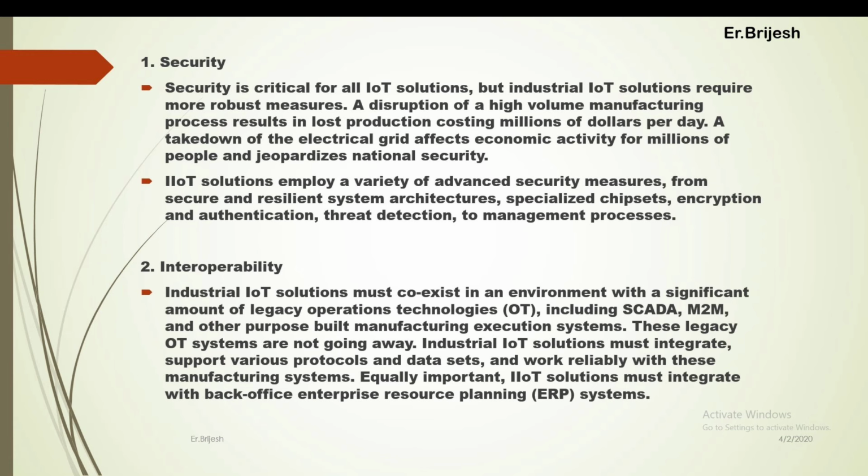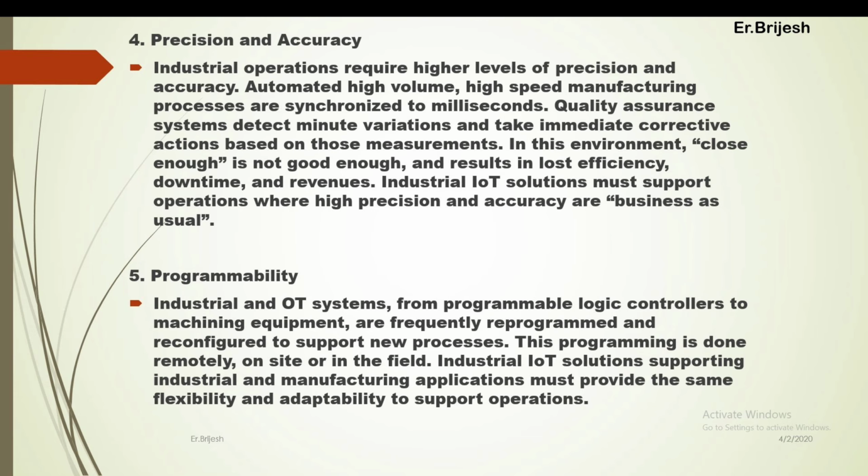Second point is interoperability. Industrial IoT solutions must coexist in an environment with a significant amount of legacy operations technologies, including SCADA, M2M, and other purpose-built manufacturing execution systems. These legacy OT systems are not going away. Industrial IoT solutions must integrate, support various protocols and data sets, and work reliably with these manufacturing systems. Equally important, IIoT solutions must integrate with back office enterprise resource planning systems.